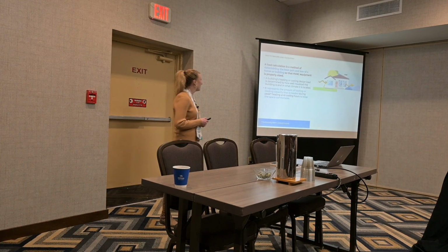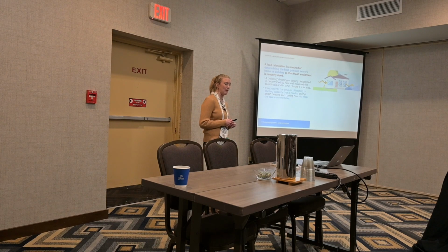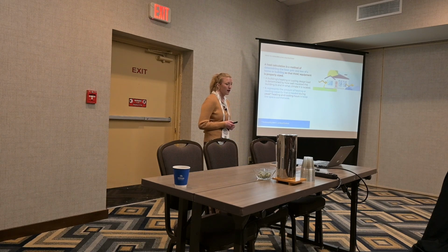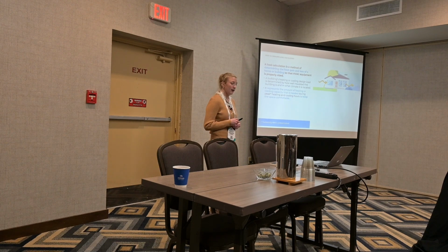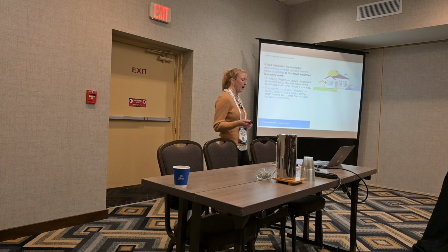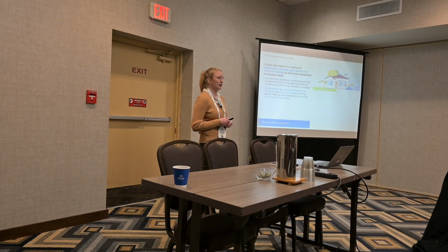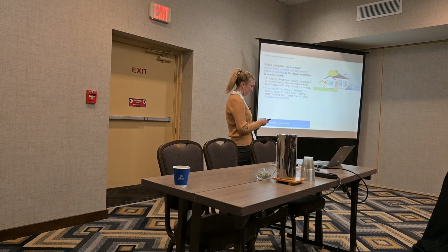So just to start off, what is a load calculation? A load calculation is a method for determining a building's heating or cooling design load, which represents the heat gain and loss of a home or building. The design load is determined by how well insulated the building is and in what climate it is in. It represents the amount of heating or cooling capacity that is needed during peak heating and cooling season for a home to keep it comfortable.